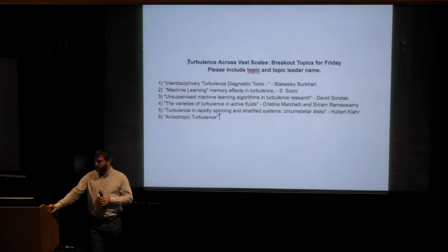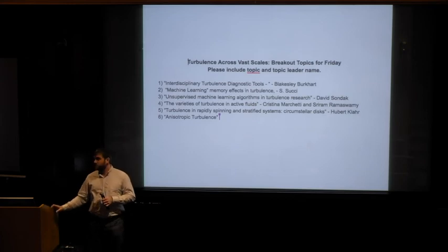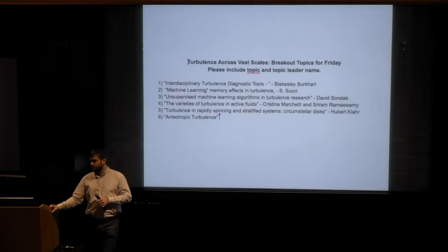Especially because, for example, the SPH code has this artificial viscosity, which prohibits the generation of turbulence. It's just not very good at capturing shocks and the generation of turbulence that results from that. At the end of the day, it was the result of entropy not being conserved. If you impose an entropy conserving scheme on SPH, then it improves. It starts to agree better with grid-based techniques and so forth.